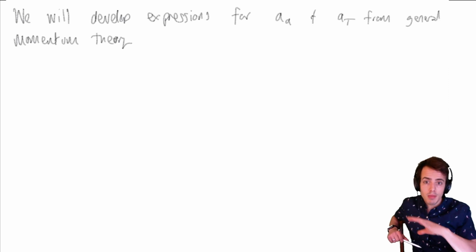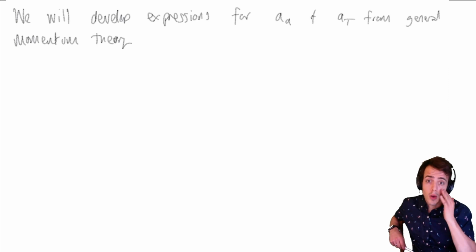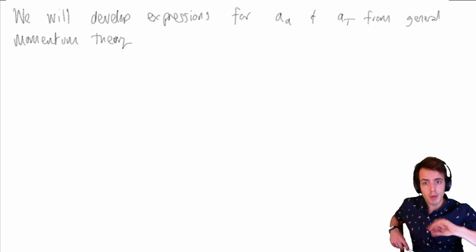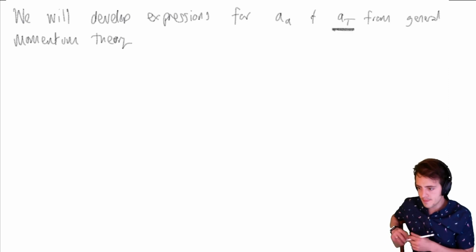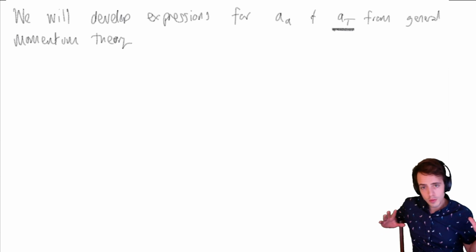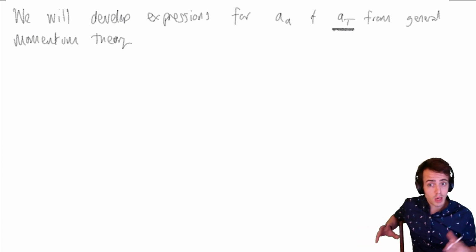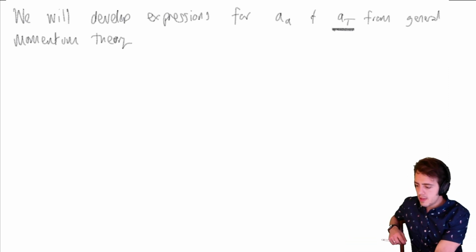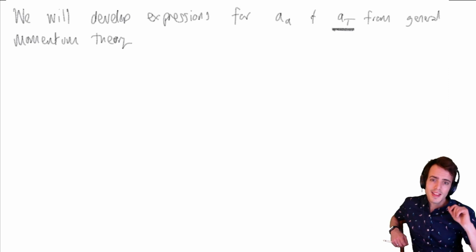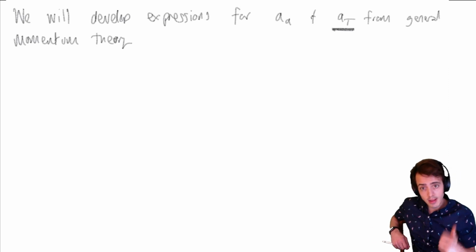It was extended by Glauert in, I think, 1926, so coming up for 100 years ago, to include a swirl velocity component. Including the swirl is what will enable us to determine the tangential induction factor. We're going to make some assumptions to allow our model to work, and we're following the theory of Glauert. The nomenclature is slightly different. Like I say to you guys, I've included my dissertation in the papers repository for this course. Appendix 1 in there is a detailed derivation of a differential form of this model.